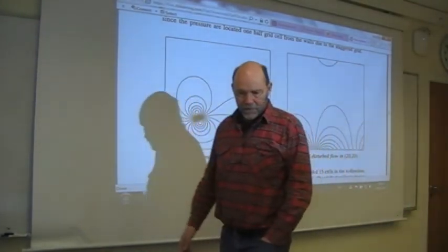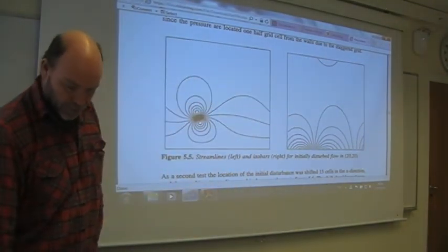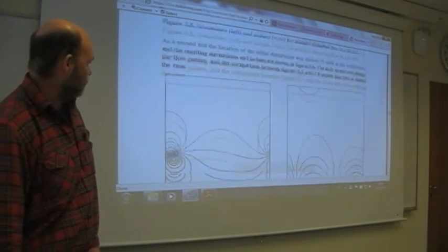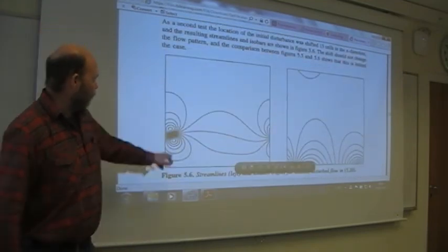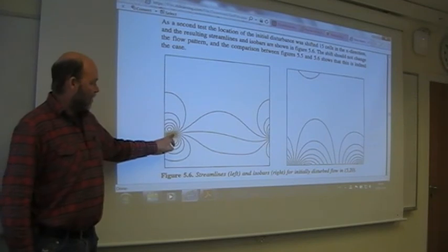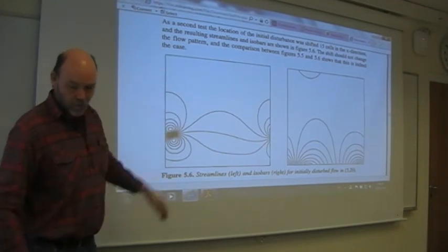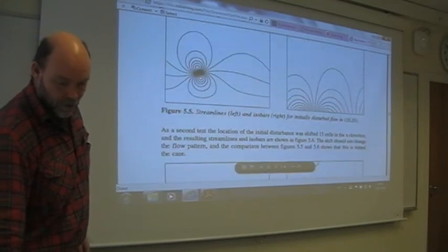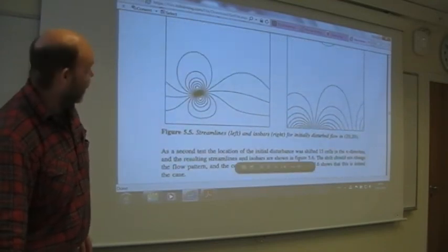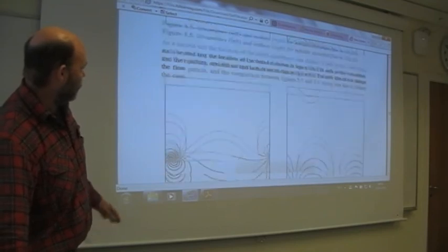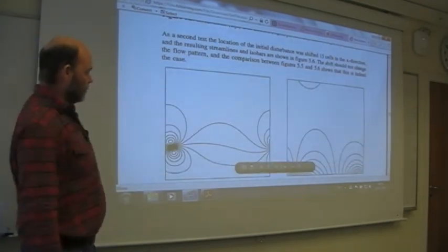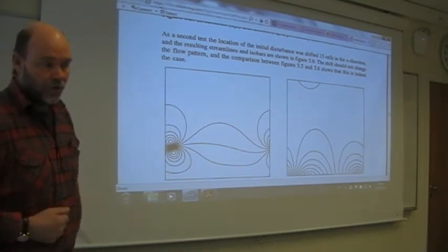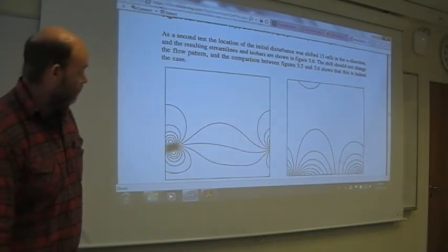And then you create the exact same disturbances, but you move the position in the x direction. So here I moved it to this one. And now these two images should be identical if you have the correct boundary conditions. And if you had made a copy of one of them and put it on top of the other by just moving it, you will see, yes, they are perfectly the same. So it's a very easy test case for periodic boundary conditions.